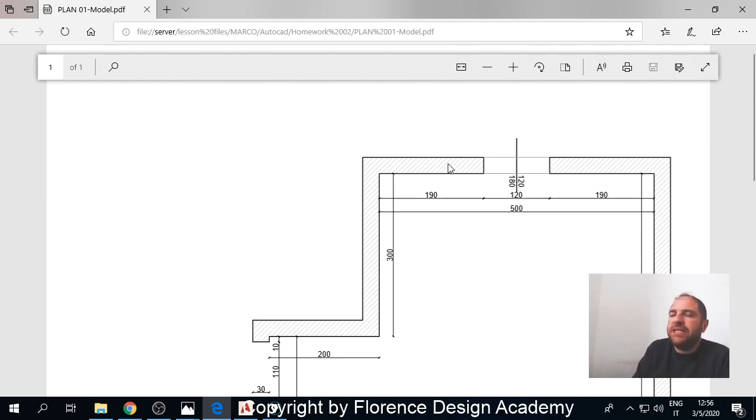So just as a good rule, you need to start from thicker and divide all of your line weights by 2, or the opposite, starting from the thinner and multiplying them by 2. So 0.1, 0.2, 0.4, 0.8, or 0.2, 0.4, 0.8, 1.6, stuff like that.